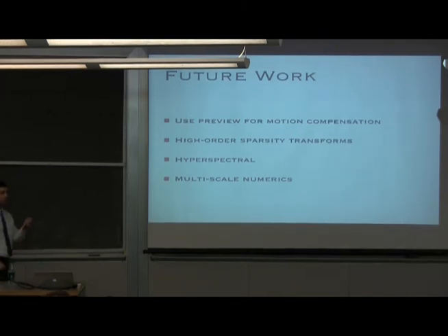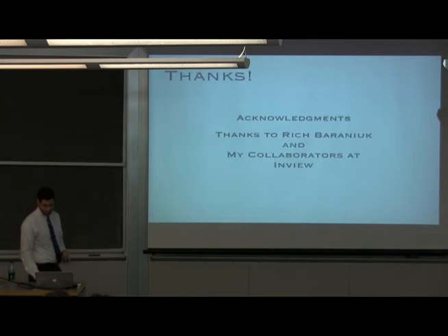Finally, some of our funding right now is to do hyperspectral imaging. So we'd actually like to build hyperspectral cameras that work in the compressive domain. And hyperspectral imaging is very expensive because of the types of detectors that you need to work over a very wide range of wavelengths. But by using compression in the hyperspectral domain, it's possible to use much more simple detectors and still do hyperspectral imaging. And finally, we would like to do multi-scale numerics. We'd like to be able to use this low-resolution preview property to use the low-resolution reconstructions in order to enhance the speed of the high-resolution reconstructions, and that'll allow us to get up to even higher frame rates.